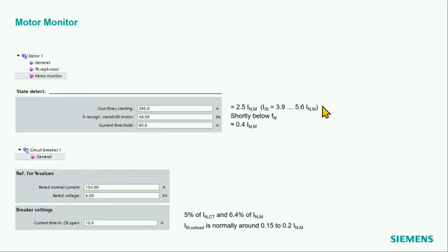So I took here the complete range, 3.9, because there's enough space towards the nominal current, or, let's say, what I assume is the maximum load current of this motor ever. And this is maybe 10, 20% above the nominal current, not more because of the K-factor situation, class F and B, this discussion.